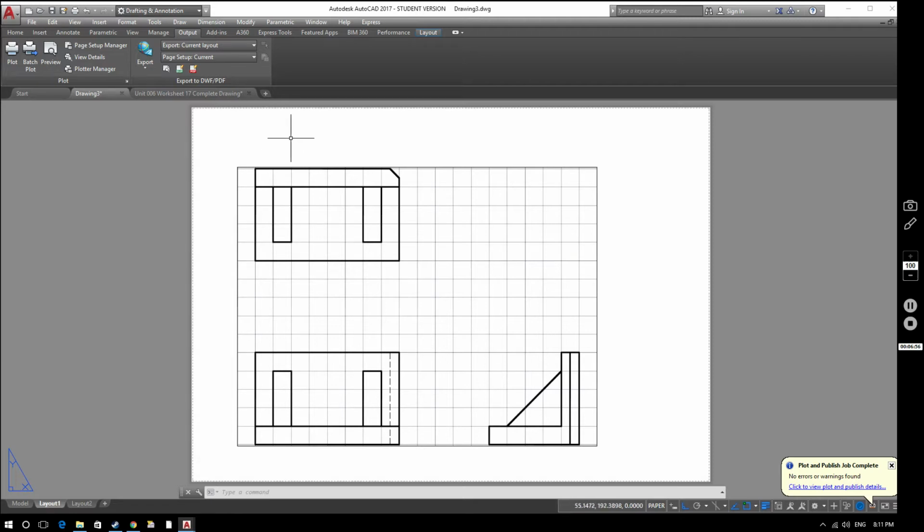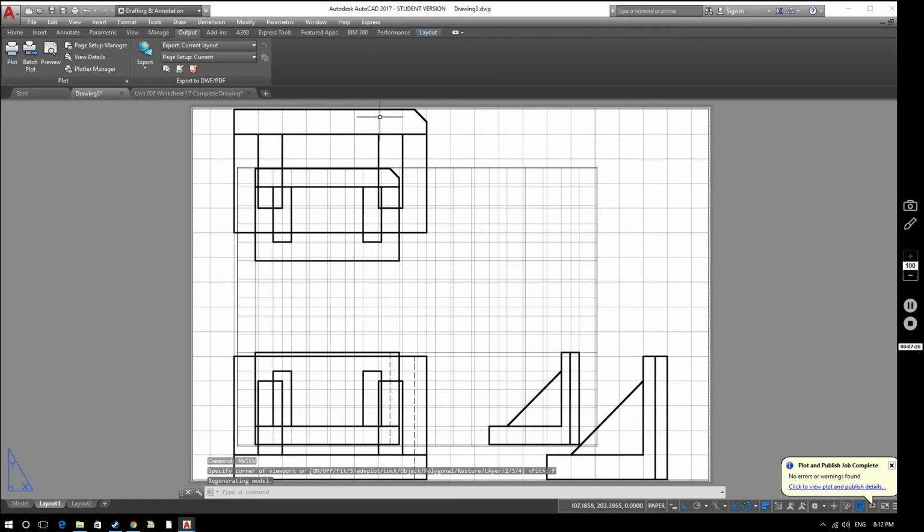What I'm going to do is create a temporary viewport. Before we get into placing viewports specifically, I'm going to just create a viewport temporarily. If you type in MVIEW into the command bar and hit space for enter, you see we've got these options now: specify the corner of the viewport, fit, shade, plot, lock, all this information. If you click Fit or type F, it places a viewport that's automatically showing the extents of our objects that we've produced, and it's snapped to the printed area.